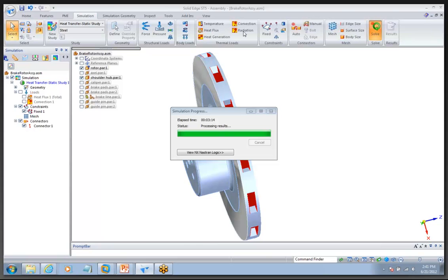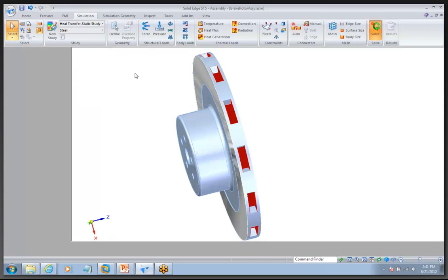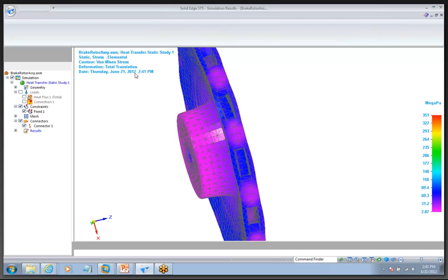Now, the last form is radiation. With radiation, you've all stood out there in the sun. It's just electromagnetic waves carrying photons, so you don't need a medium for them to transfer through. And you've got the Stefan-Boltzmann equation, which says the surface temperature to the fourth power times the Stefan-Boltzmann constant, and then you multiply that by emissivity to get the heat flux. Emissivity is another material property that you look at, and an ideal radiator has a value of 1. It radiates perfectly. So everything you're going to do is going to be below 1.